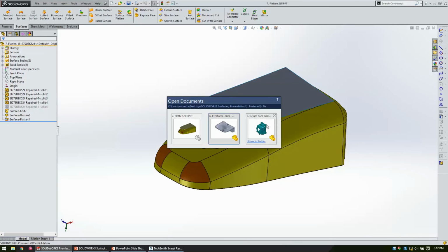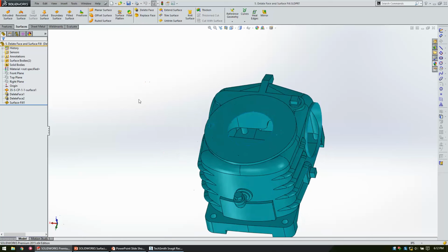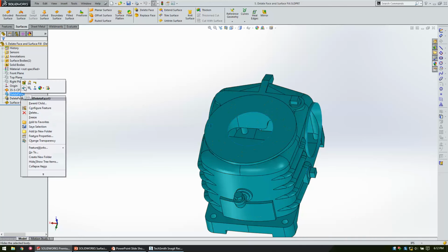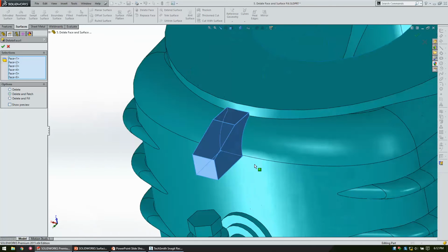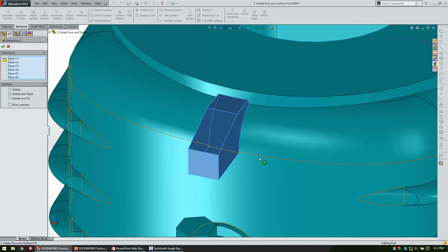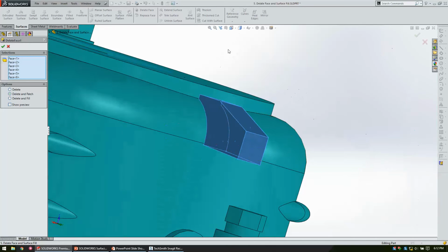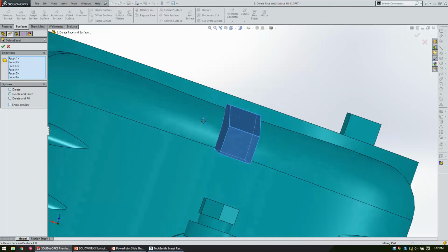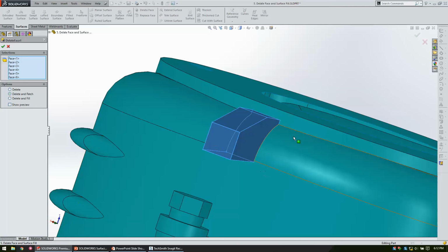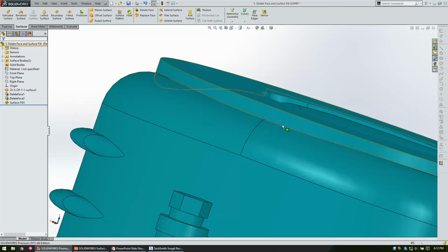All right, moving on. So this is your delete face and fill. So whoever asked the question there in the back, this is where I would use it. This is where we have a delete face that spans multiple faces. So I don't want this block sticking out here on this downloaded cone gearbox for whatever reason. So I can pick all of these faces, even though it spans multiple surfaces. And if I select patch, it will just close.